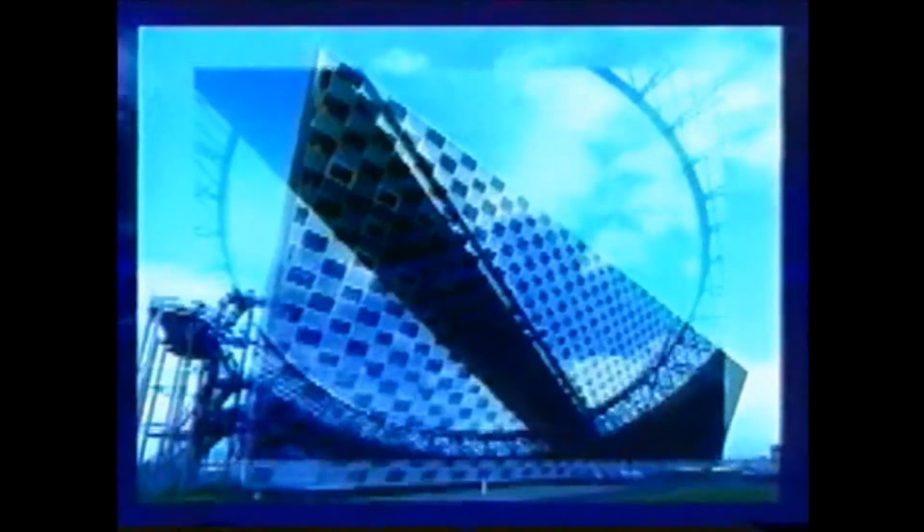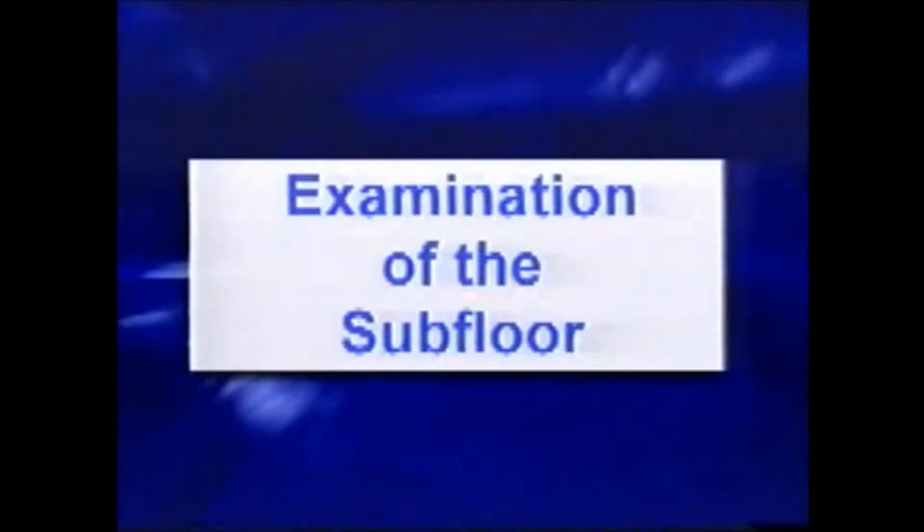During the design phase, the architect and the contractor must select the type of floor covering according to the intended use of the area. Construction or renovation of the building will be subject to on-site supervision by all specialized trades under the oversight of the contractor or of the architect. After the concrete slab is poured and dried, and after the work of the other specialized trades is completed, the installation of the resilient floor coverings may begin.